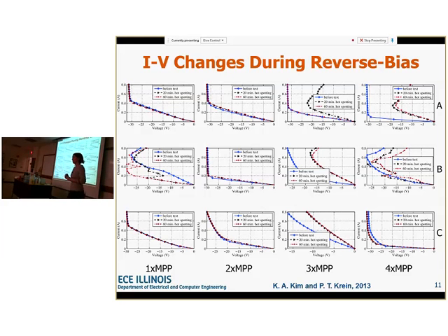Did you make up this term, second breakdown? No, that's actually a real term. Second breakdown is where instead of going through the whole area, it goes through one little point. It's for transistors. A lot of old literature has that terminology, and it's a failure within a transistor, and it will heat it up quite a bit. So essentially the same thing, only in our case PV is essentially a giant diode, so it just goes to one little corner instead of a small die.